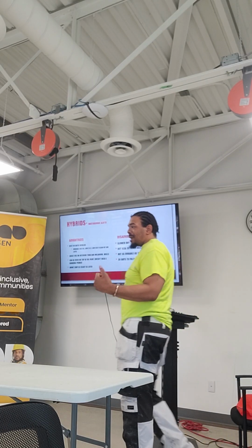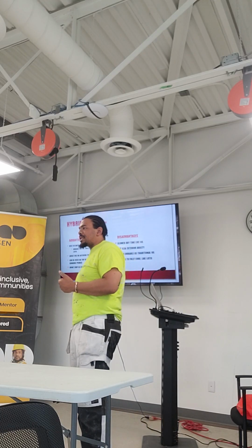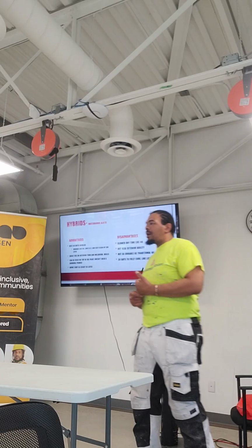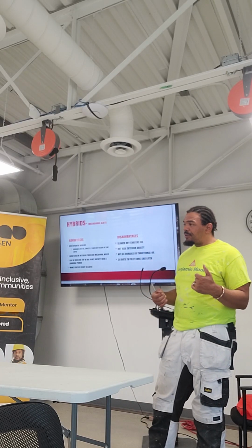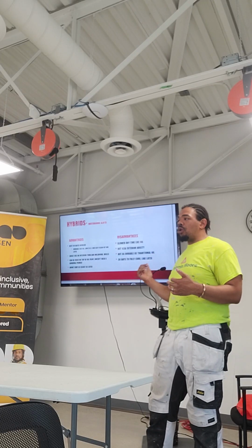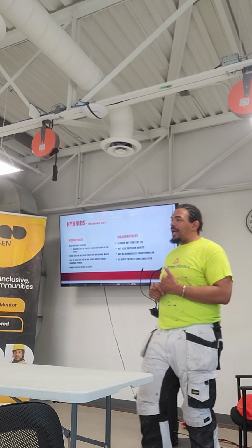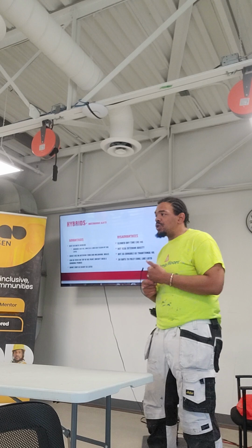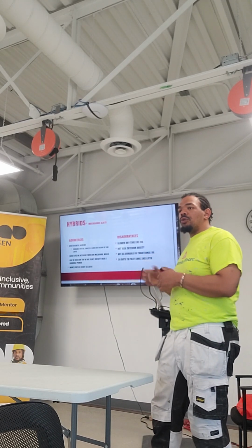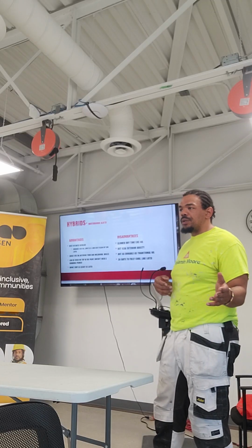a bonding primer. What I love about these hybrids is that we talked before about latex paint going over oil paint and how it just peels right off. In this case, with what's called a hybrid or a waterborne alkyd, when you're applying it over an oil-based paint, you don't need a bonding primer. So you can use this material right onto oil-based baseboards.